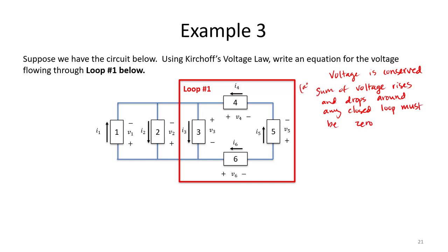Again, this is the algebraic sum. So the strategy I like to use here is to walk around the circuit. So we want to walk around the circuit and sum the voltage rises and drops.